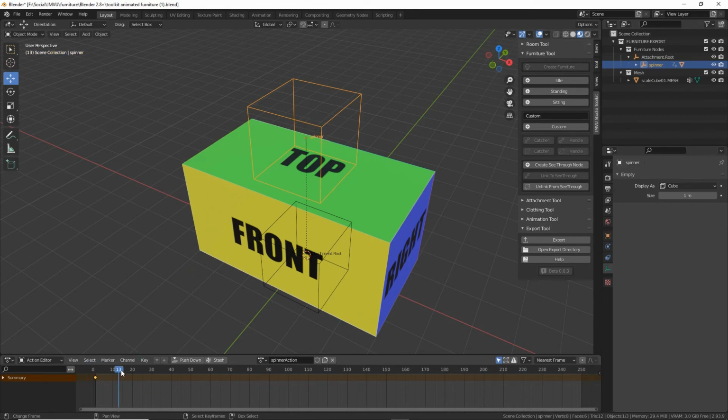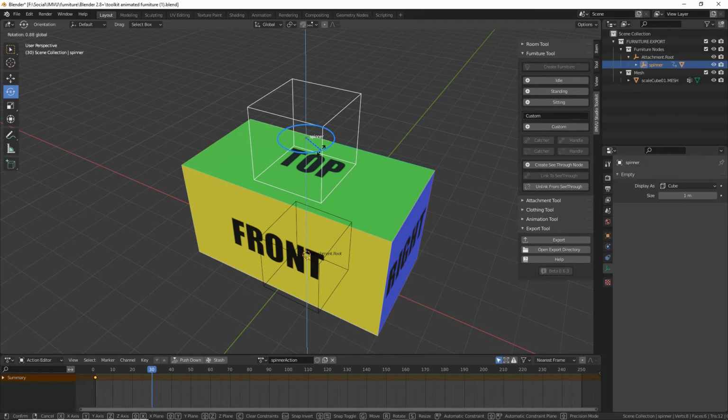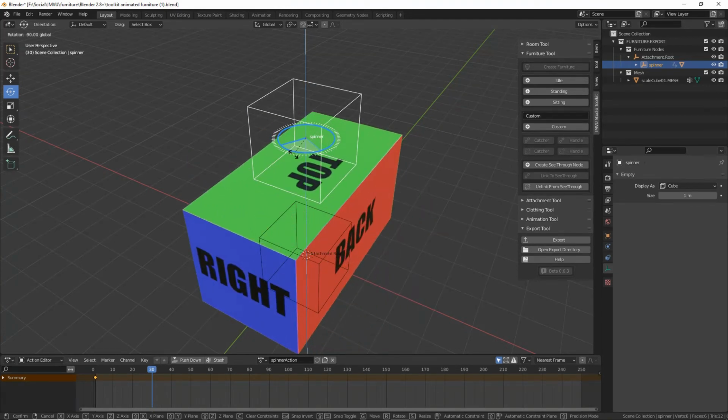So grab the timeline scrubber, move it to frame 30, and let's rotate this. So we're switching to the rotate widget. We're just going to click drag the z-axis and rotate around that, holding control so we snap to the grid or increments, and rotate that by 90 degrees. So if we watch what's happening at the top there as we move, we can rotate by fixed amounts.